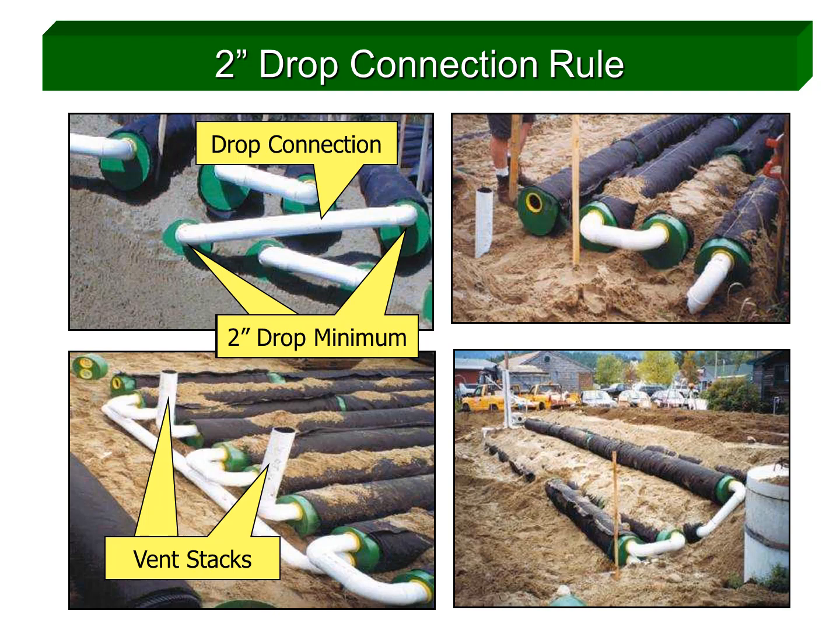It may be necessary to utilize a combination configuration, even when one isn't required, to make sure this rule is honored. For example, if the field is placed on a steep slope but only requires basic serial distribution due to a daily flow of only 450 gallons per day, the preference would be to feed the lower level from the lowest row of the upper level, as shown in the upper left picture, and have the minimum 2-inch drop in elevation. If this can't be done, a possible solution would be to use a combination system and feed the upper and lower levels separately.